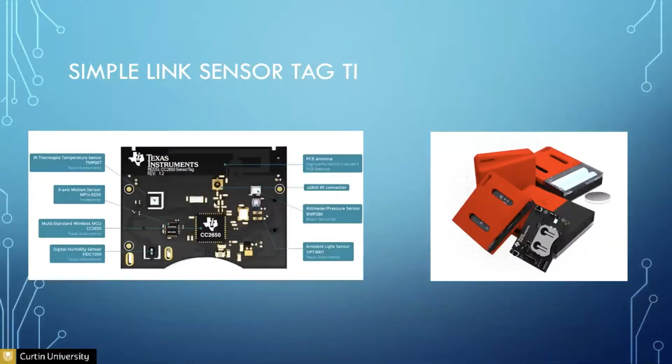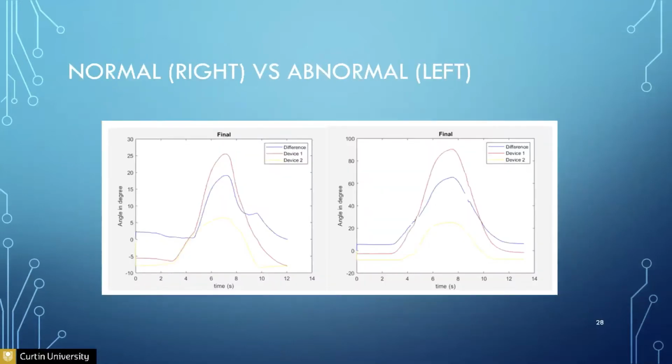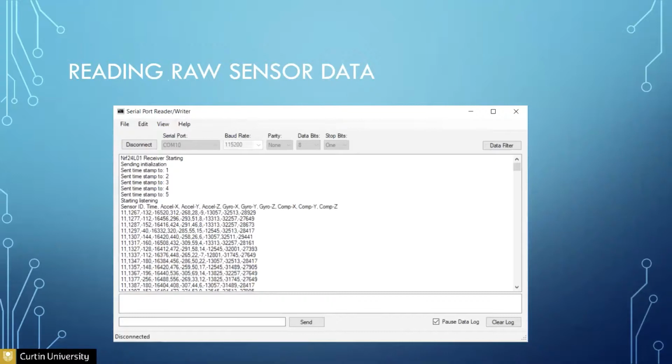So because I have very little information about this equipment. Yes. Have you had a chance to take a look at the links that Ian and I sent? Yes, I read about them, but I also have very little knowledge about them. Okay, so what I'd recommend, a good place to start with that, don't worry about the IMU part. Just have an RF transmitter connected to one Arduino, or are you using an Arduino as your platform, or is it ESP32? Yes, Arduino. I already get all the sensor data. I see. Now I understand. Yes. So now to practice the data sending and receiving, don't worry about your IMU. Just connect an RF transmitter, or if you were interested in working with a Bluetooth sensor, there was also a Bluetooth sensor in one of the links that I sent you.